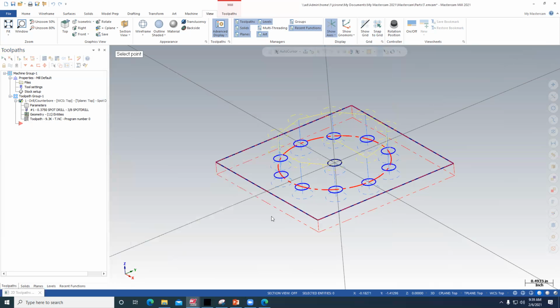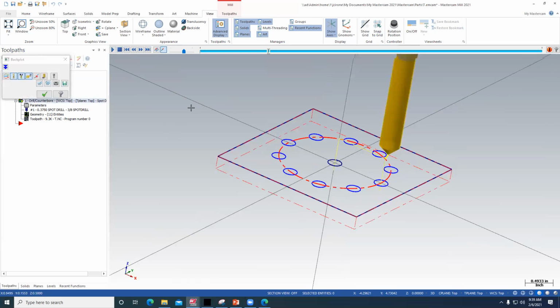Don't spot. And again, something that is greater than a quarter of an inch because it's the drill size. So it's like 3/4 inch. Now check what size spot we have in there. It's 375. Spot. You want to match the tools to the ones you have in the shop. It's a very important thing because if you write programs for tools you don't have, you know, so we check. Okay, so now we have a spot.